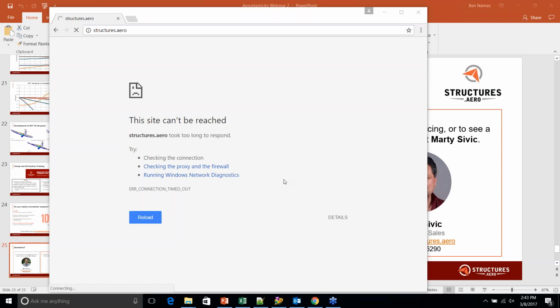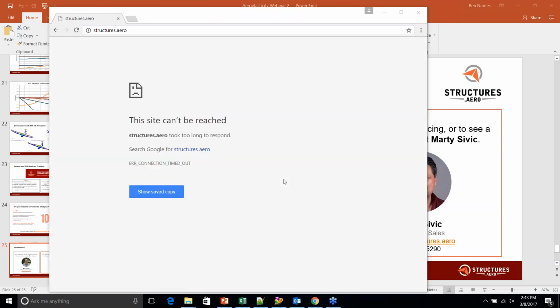Okay, interesting. Yeah, so this is aerodynamic damping. This is not structural damping. That's a really great question. Often you can consider the structural damping, unless you really want to get into the nitty-gritty. The structural damping can be introduced as just a proportional, say 1%, usually anything reasonable is between 1 and 5% proportional of your stiffness matrix. If you want to get a little bit deeper into that, you can, but you do not always need to. Often that gets pretty deep.